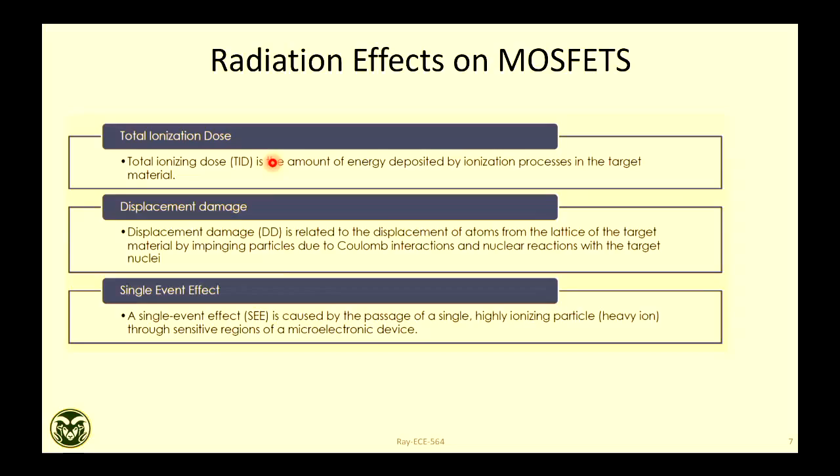Will threshold voltage increase, decrease, or remain the same if there is a lot of positive trapped charge in the oxide? Think about flash memory. Decrease, right? Because in flash memory we trap electrons, threshold voltage increases. Here you are trapping holes, so threshold voltage decreases. That means a programmed cell will become an erased cell after a lot of radiation. Similarly, if threshold voltage decreases, what are the other issues? You increase leakage, right? It cannot be turned off. If threshold voltage becomes below zero, that means at 0 volt the transistor is on, and a huge amount of leakage will take place. So it will cause your DRAM retention issues, SRAM noise margin issues and all.